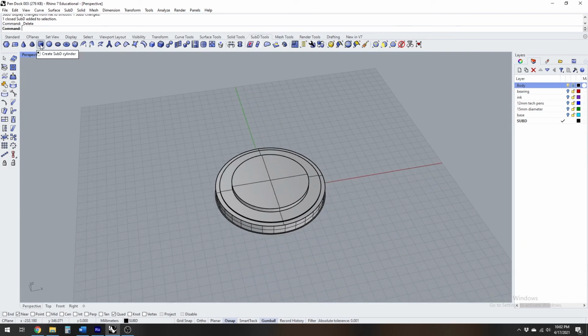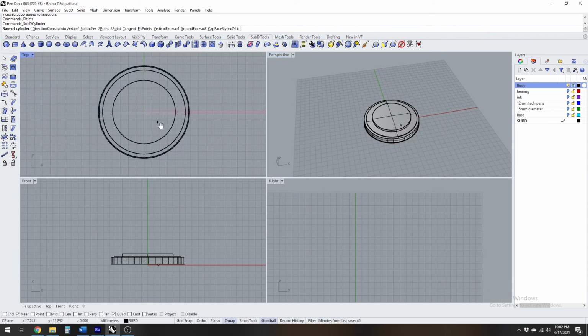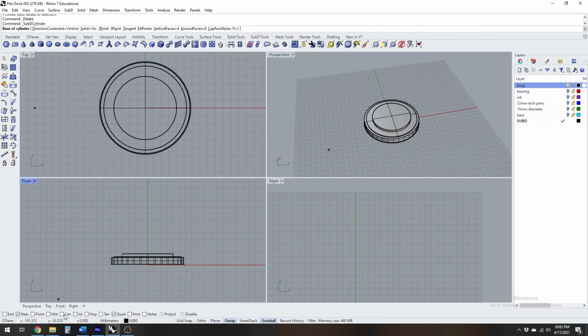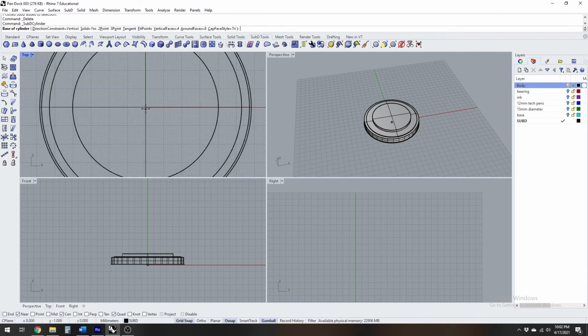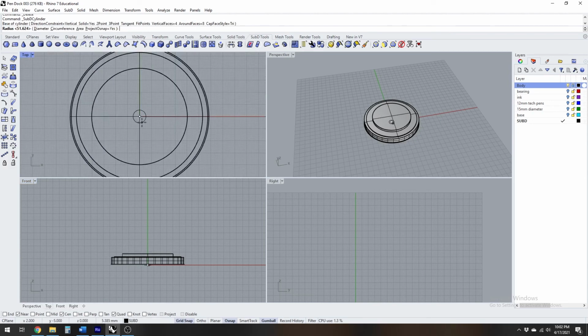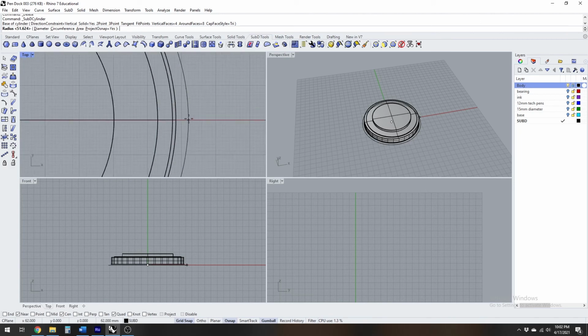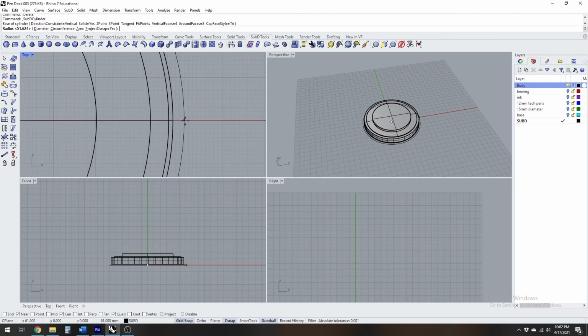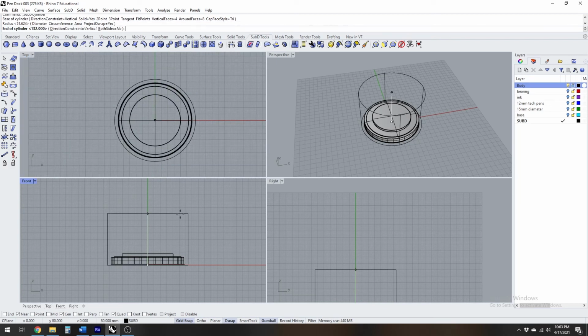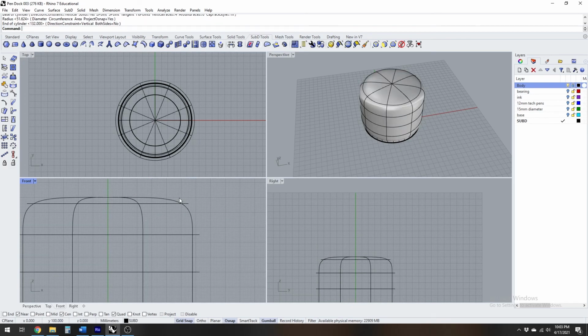So I'm going to do a cylinder here, and there's going to be a compromise. You're going to see that when we create the cylinder, the points that we start from, center to edge, are not going to be exactly where the cylinder is set. We're going to have to do a little bit of scaling after the fact. See how I'm setting it to this exterior edge here? Then when we select it, the made cylinder will be ever so slightly smaller because of that smoothing action. See? There we go.